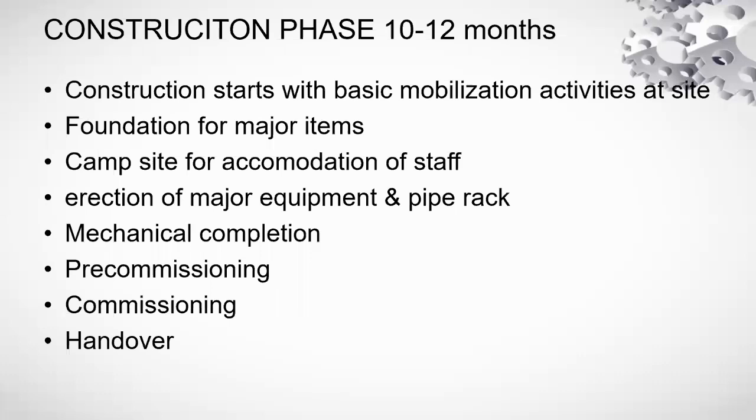So these are very critical stages, pre-commissioning and commissioning, and they are very intense compared to the construction phase. These involve a lot of brainstorming sessions during pre-commissioning and commissioning. And the last stage is guarantee run and handover. At this stage, the plant is handed over to the operating company. Sometimes this involves another 6 months extension from the commissioning teams to give training to the staff available, or if the staff is new.